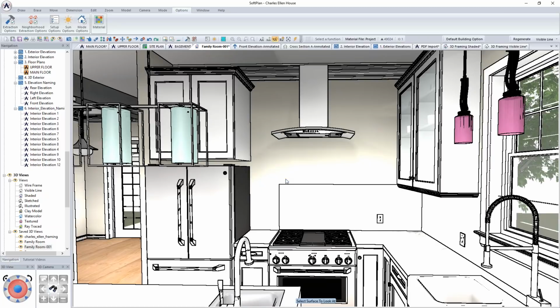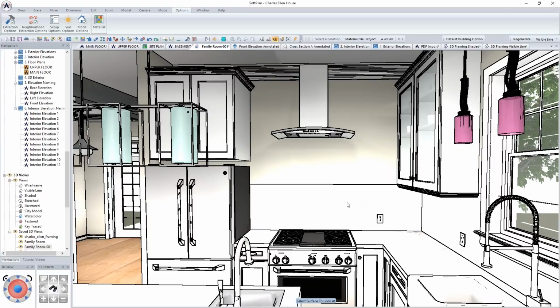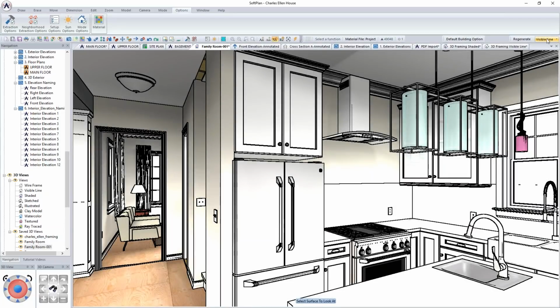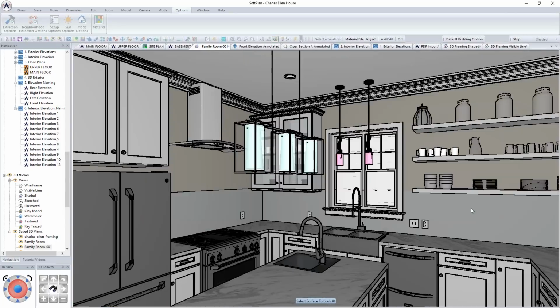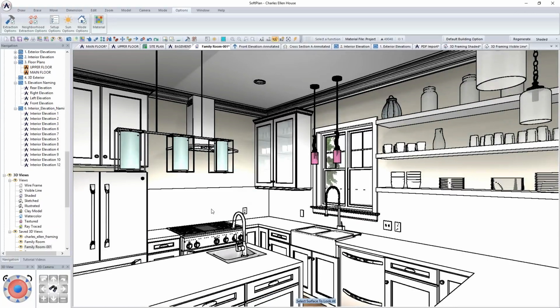And of course, then this cabinet here, I would simply come into the same accessories, tile backsplash, and I'm just going to add it. I could have the option of having it covered to the right and so on, but I don't need it because this one's covering to the left. And so now we have our tile in there, and all I would be left to do is add a texture to that as far as the model is concerned. Whether it's going to be tile or whether I'm just going to have the counter run up there, that's going to be found under your tile backsplash, and then you can go to the accessories and have that done on the model itself. Okay.